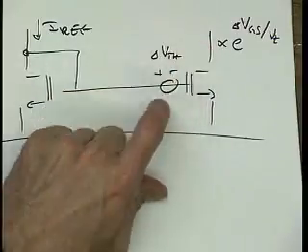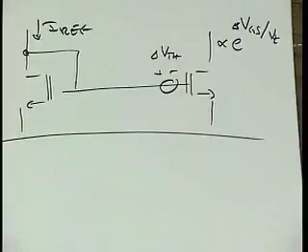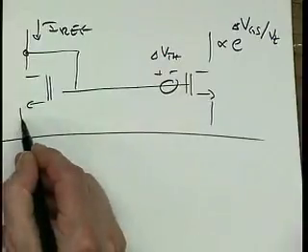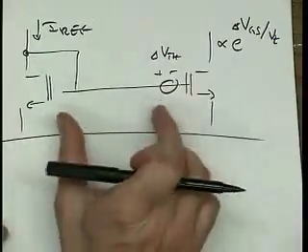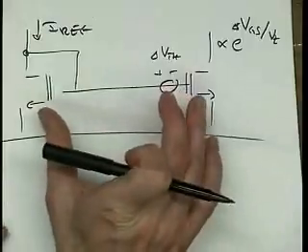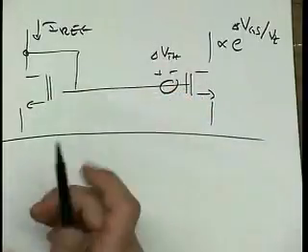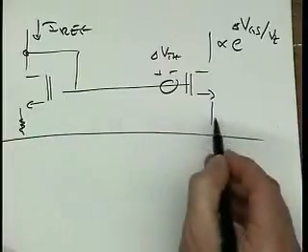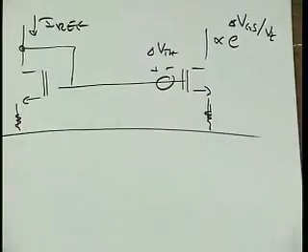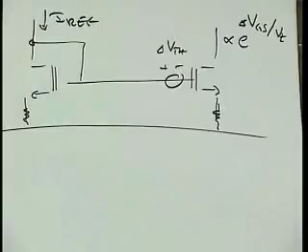So it's very sensitive. In fact, in bipolar devices, it's not quite as bad because VBE mismatch is smaller than VTH mismatch. But even in bipolars, they put resistors in here. Now, we could do this resistor business also with MOS. Would you do this?